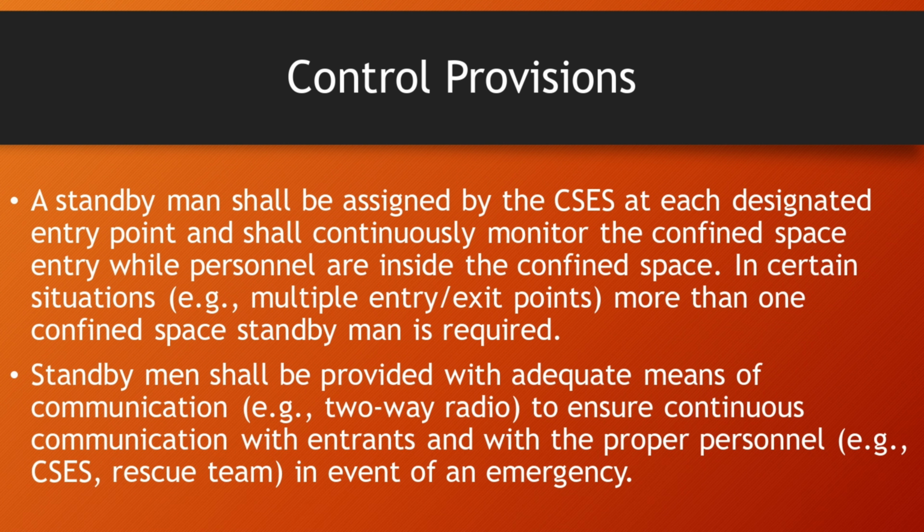A standby man shall be assigned by the CSES at each designated entry point and shall continuously monitor the confined space entry while personnel are inside the confined space.